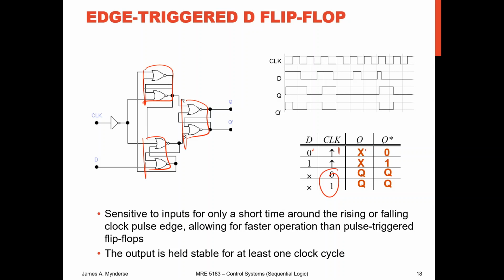So you can see that in our timing diagram. You're looking for these rising edges of the clock, and so you can see that your output is going to be aligned with those rising edges. And drawing a few more there, you can see that it's aligned there. When things happen like here between the rising edges, they're simply not captured. It's happening too fast to be captured by the clock. So you do want your clock to be reasonably quick.